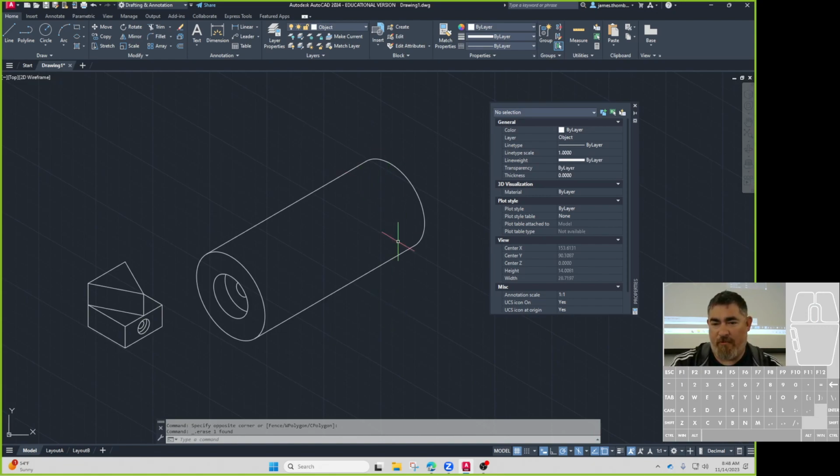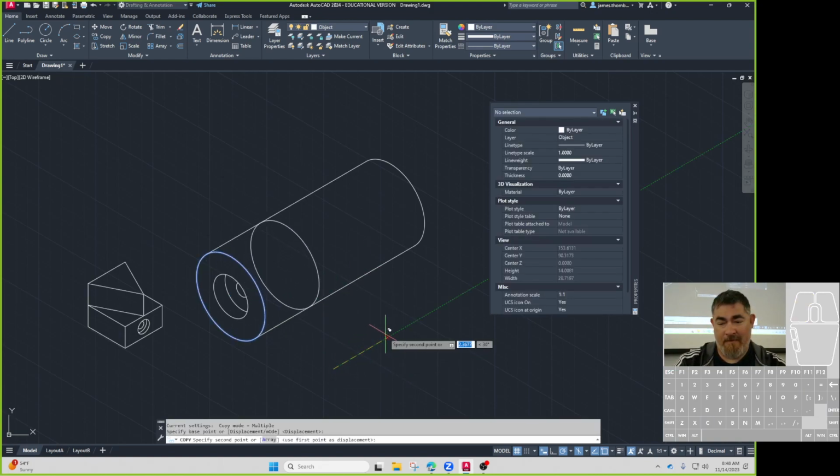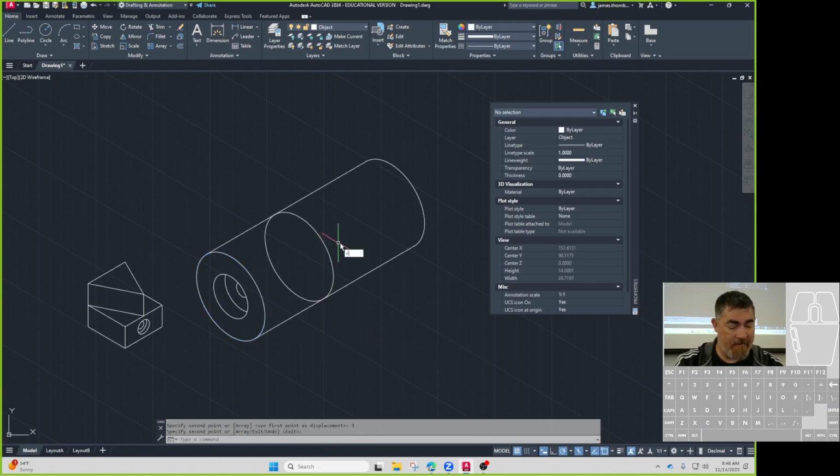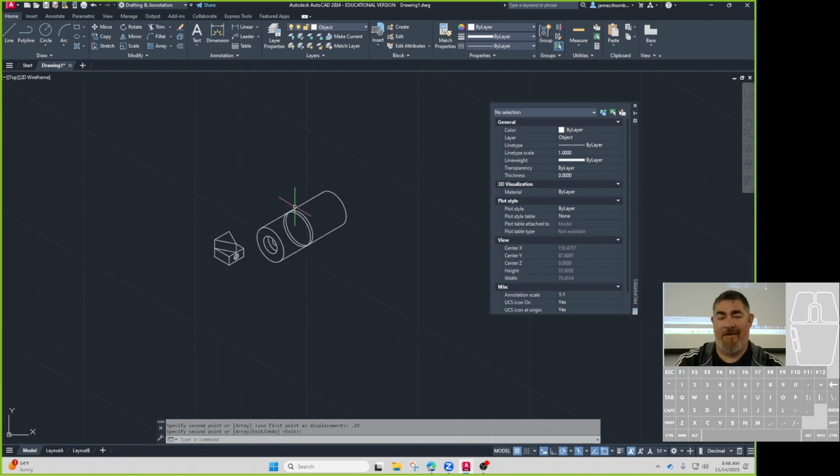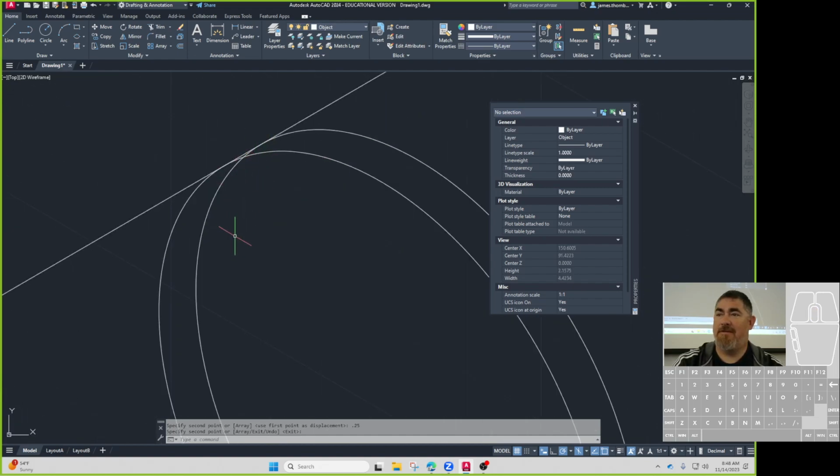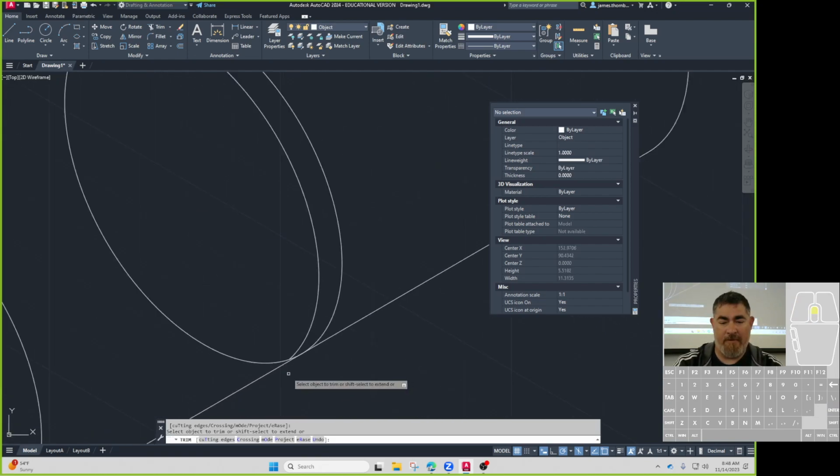So, what if I was going to have a groove around this? I need to have a little inset groove. Let's see, over here I want a little square groove going around it. Do the same thing, just copy this. And let's say I want to go back 3 inches, and I want the groove to be 1/4 inch wide, right? And then I just need to control how deep it is. I know that between these, it's probably going to go away, but I'm probably not going to need that. So I'm going to get rid of that part of it.